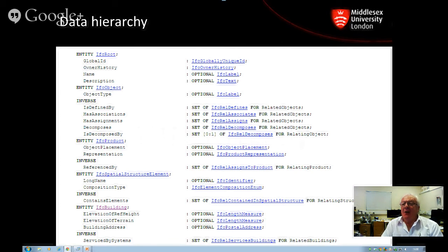Well, Mohammed, you'll be putting graphics together in a 2D world in any case. So you put the 2D graphics together just as you would a 3D object: a door or a chair or a column. Make sure that whatever system you're using has a container for information in a 2D world, and that the container contains just the information about that element. So often in the old 2D world, people stuffed everything on one layer and, a bit like the paper drawing world, hoped that all the information you needed was there somewhere. And if you stick it all on one layer in a 2D world, you can't sort it. You can't supply other people in the project team with the precise information they want. So all these principles apply in the 2D world just the same as the 3D world.